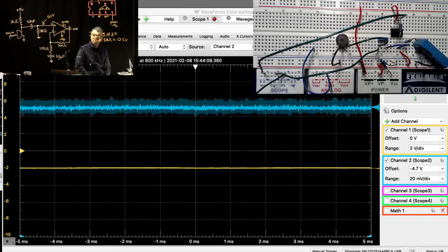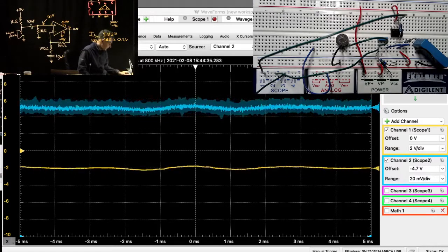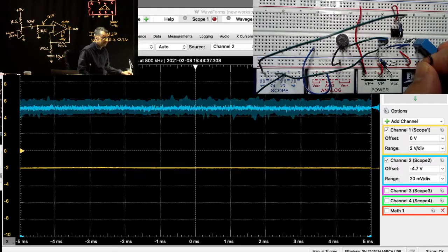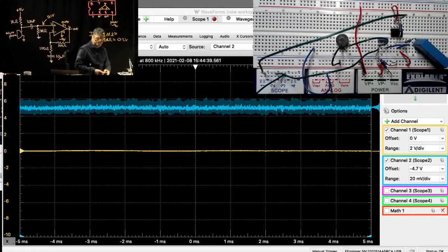Maybe I bias for this particular 741 amplifier is only like 20. Yeah, maybe this particular op-amp has only like a 20 nanoamp I bias. Although I think we've measured more like 40 on most of the ones that we've pulled out of the drawers in the past. Anyhow, you do see that there's a significant DC offset. It's not as big as I expected it to be, but it is significant.